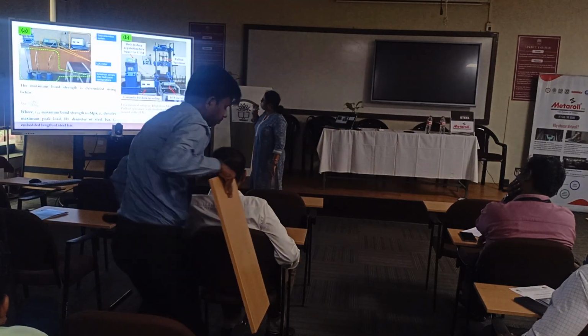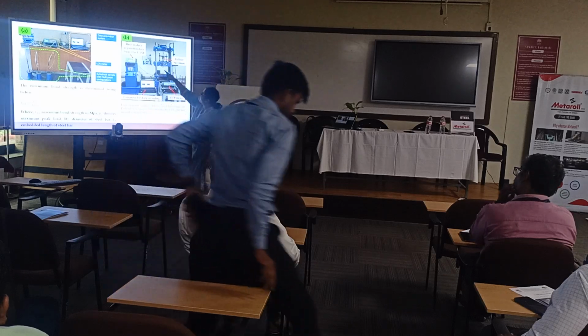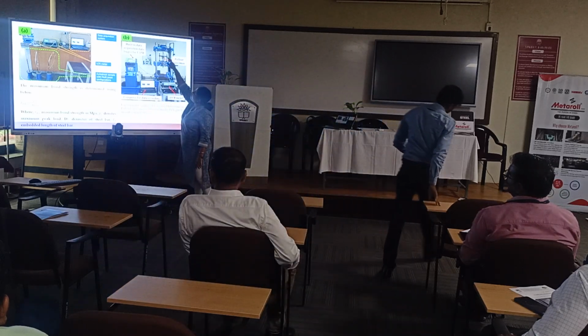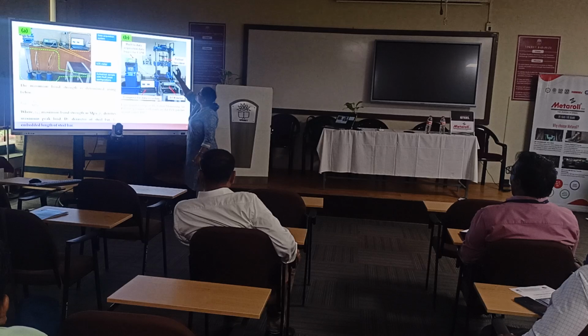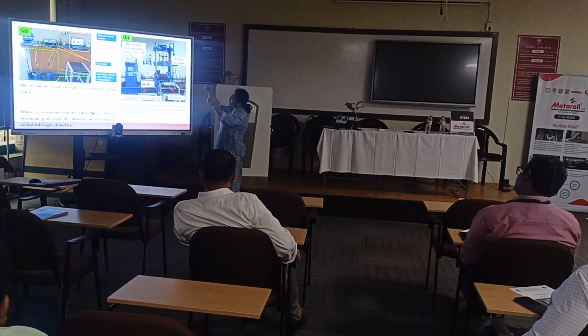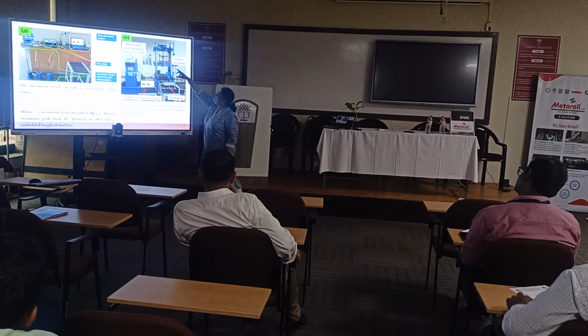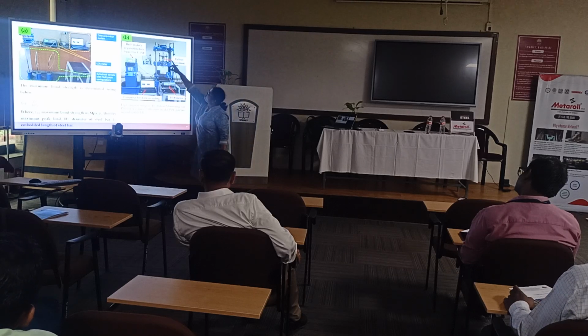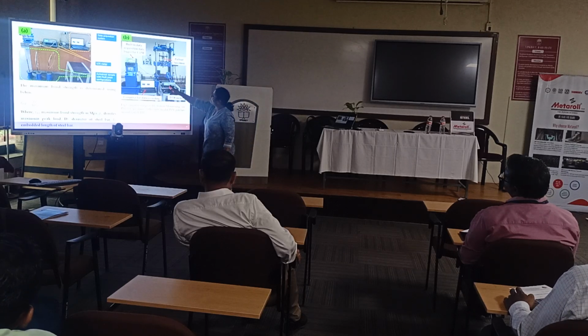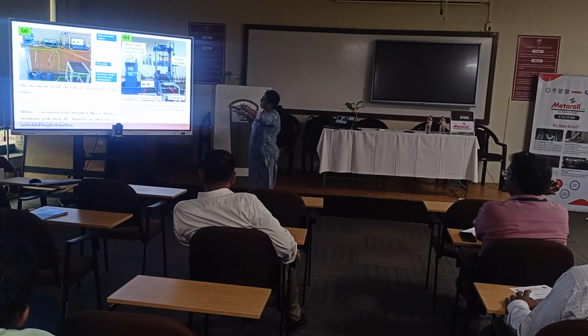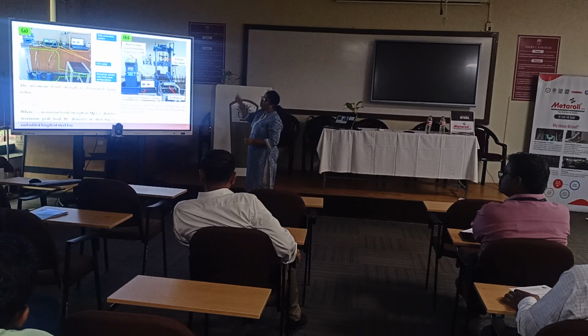What we do here, you see we have two steel plate attachments, with two screw-threaded chains connected to the plates at the two ends. The pull-out specimens are stationed in the middle, and the sensor wires are integrated with the LCR meter. We also have an LVDT attached to the top plate of this pull-out specimen arrangement, and we apply the tensile pull.